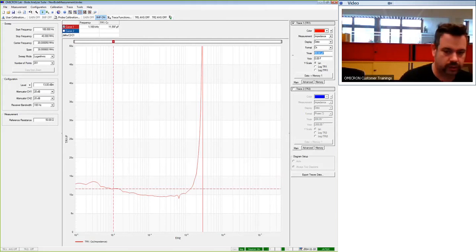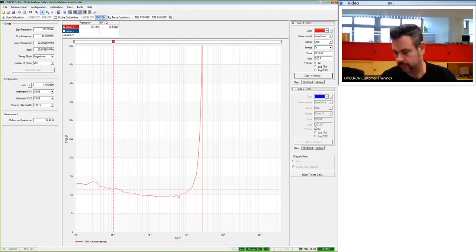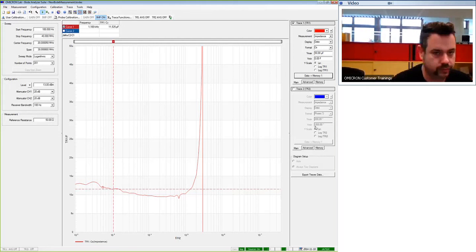And what we can now see very nicely are these bumps. The bumps you can see here are caused by the probe calibration. Since this bias injector has a capacitor itself in it, and we are measuring at very low frequency now, the capacitor already has a high phase shift, and so it's not linear anymore. So we would need to do a user calibration to overcome these bumps.